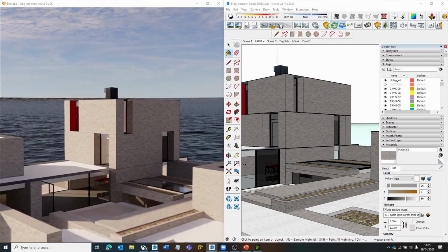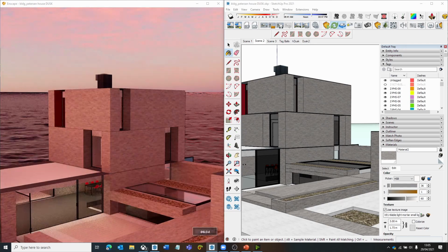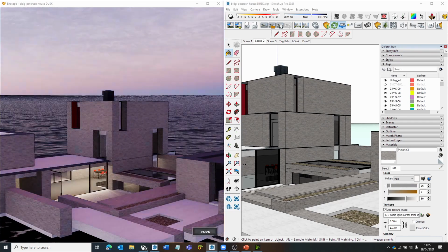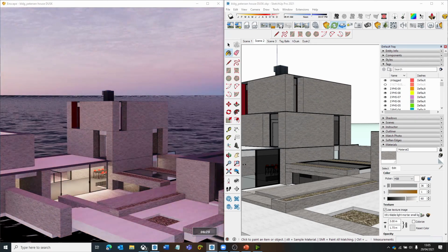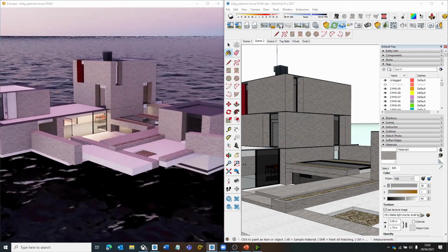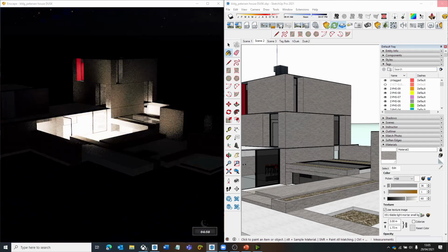We can now see that, even between SketchUp and Enscape, this more easily reads as brick. And we can also see that as we're changing the lighting conditions across the model, this is behaving in a reasonably natural way, and things are looking quite nice, even as they should do. What this has highlighted, though, as we've brought the brick into a range of brightness that is more appropriate.